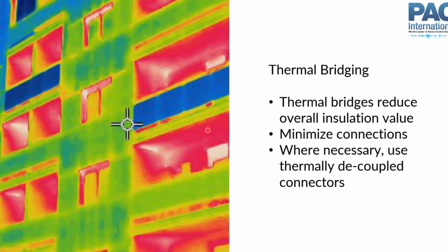And if you can decouple those thermal bridges, and there's a whole bunch of different ways that you can do that, and that's not my area of expertise, that can improve the overall insulation value of your wall without changing the actual thermal insulation that's in your cavity, because you've decoupled those structural connections. It's the same sort of thing for acoustics, very analogous. And sometimes what might work for acoustics might also work for thermal insulation.